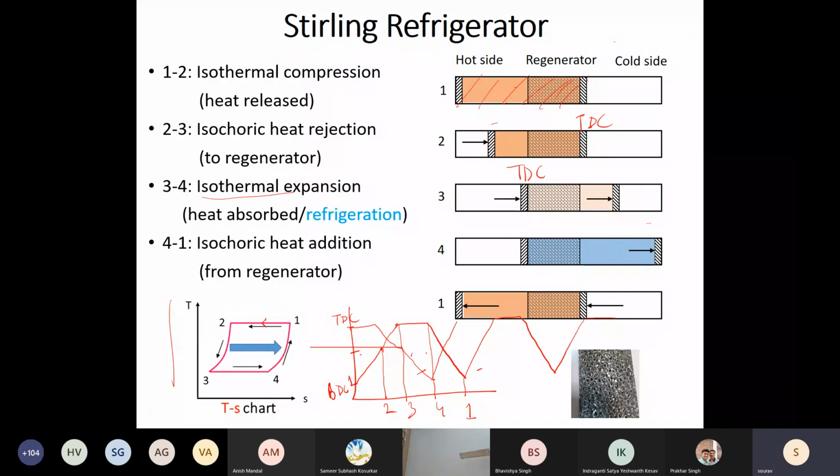Of course we are going to connect it to a crankshaft, and ultimately what we get is something of this fashion, the sinusoidal form. So we will not be able to achieve the exact positions that are desired from this cycle. So this is the next set of non-ideality. These are all from the mechanism point of view. First of all, you cannot have an isothermal process because capacities will go to 0. From the mechanism point of view, we will not be able to achieve the exact positional locations that are required for the piston. We will have to make certain adjustments.